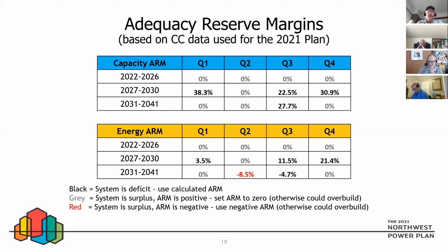So just one more point back to the imports, and I'm going to oversimplify this, but consider that we have about 8,000 megawatts of transfer capacity between California and the Northwest. Actually, the DC intertie going north is currently limited to 1,000 megawatts. You could possibly raise that. But the bigger issue is that the AC intertie is about 4,800 both directions at peak, but that's not always the case, and there are maintenance windows and other kinds of things you have to consider.